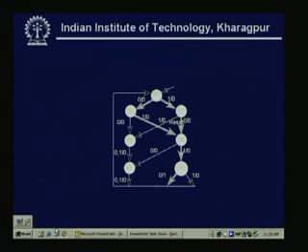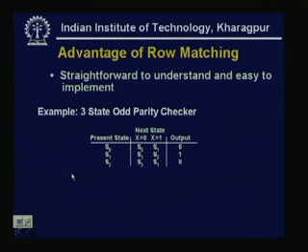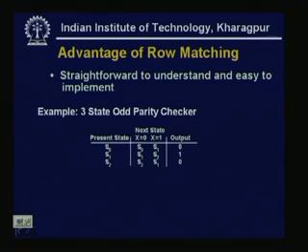So, mainly this is a very straightforward algorithm. What we have done is that for all possible inputs, we have created the input output behavior and the state transition table, and then we check whether at least any two rows exist where, for any input combinations, the output behavior is the same.